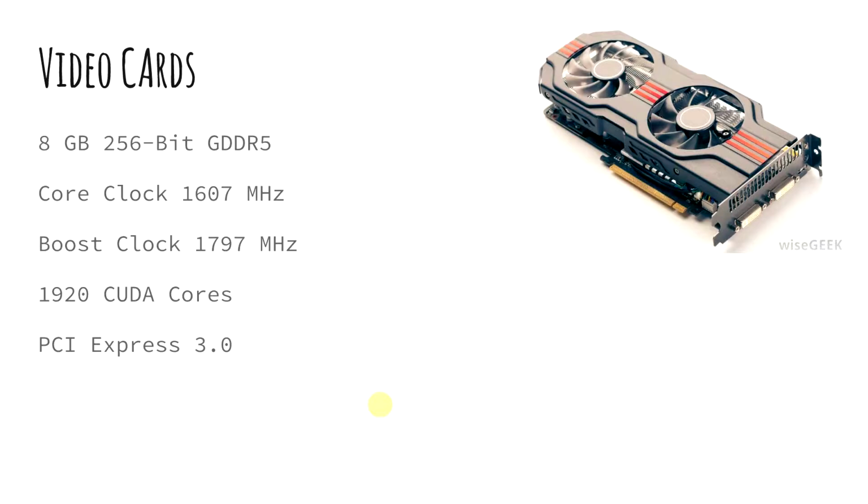Your PCI Express is the first important one. That's going to tell you whether or not this card is going to fit into your motherboard. When you first picked out your motherboard, you should have written down all of these different aspects of it and used this as your baseline. It's going to determine what you can use, as I've said in previous videos. So if your motherboard only has PCI Express 2.0, you can't use this card because it requires PCI Express 3.0. So back to the drawing board with your motherboard; you're basically scrapping the project and starting over.